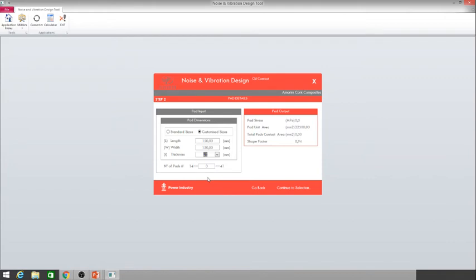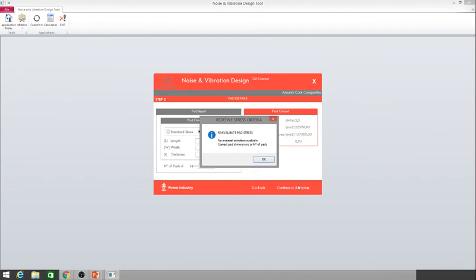And you remember we have 7 legs, so we have options from 14 to 41. But we forgot, we didn't see the 14 there, and we said 7 legs. Let's input 7. The software gives a warning to re-evaluate pad stress, correct pad dimensions or number of pads.